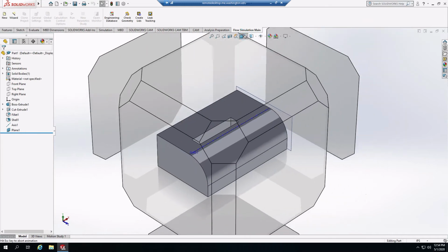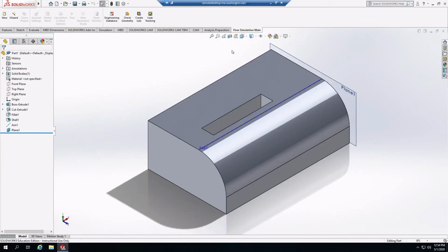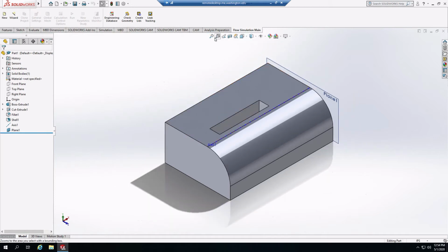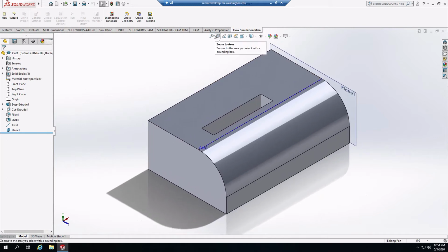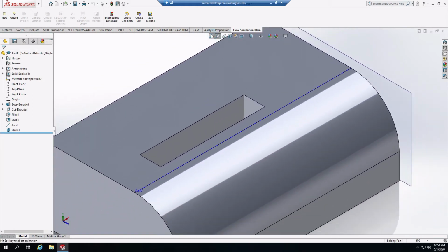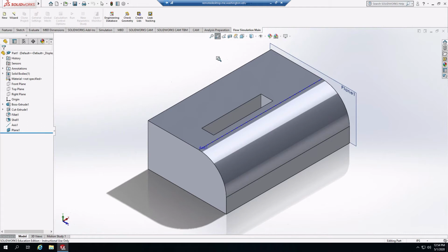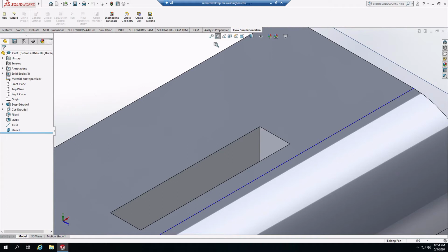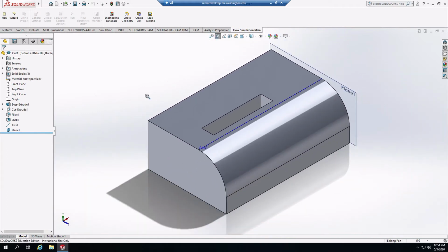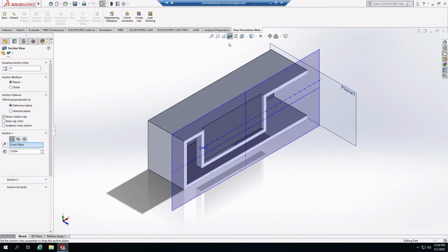Up there we can also see what we had with the space bar. You can also edit appearance. You can zoom. You can fit to view, so it just fits the piece to the frame. You can also select areas to zoom in with that second tool. So even if you don't have a scroll wheel to zoom in and out, or to press in on the scroll wheel and orbit around, you have a bunch of tools you can use.